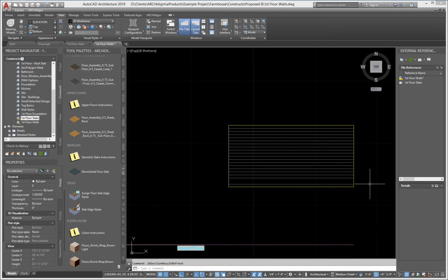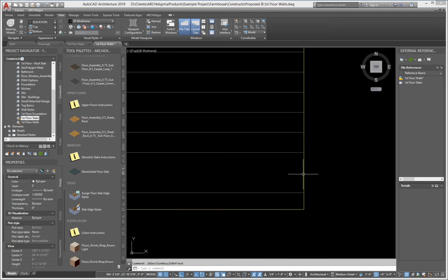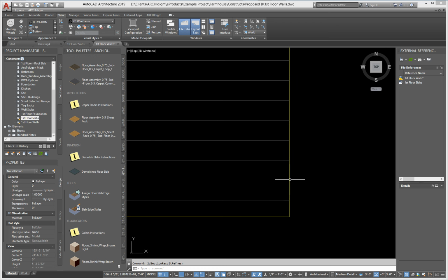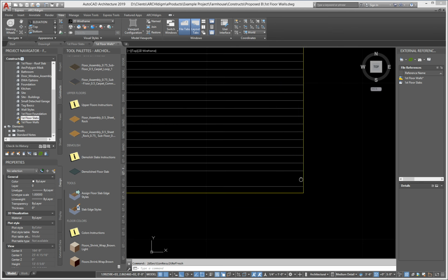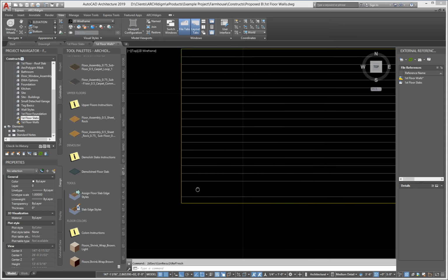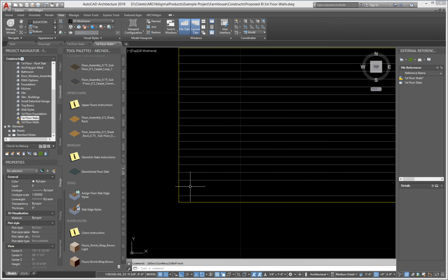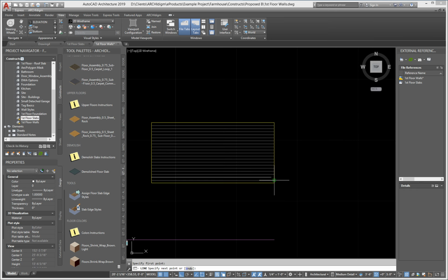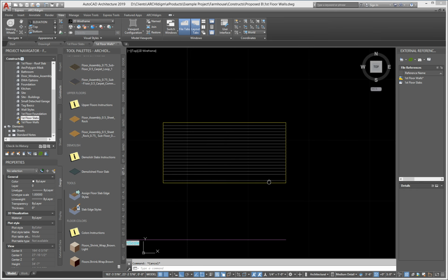Okay, so this is where it starts to do some undesirable things. What unfortunately is occurring is right where that horizontal line should show as a hatch pattern is the seam between the slab and the wall. So you don't get anything there. I used to just draw something in there. I would figure out right where I wanted it, and I would just draw something across, and that's still valid.